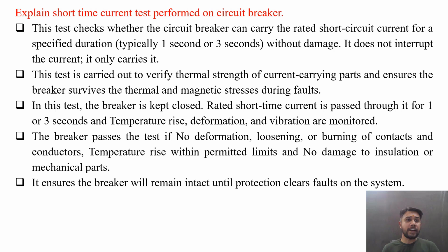It does not interrupt the current, it only carries it. This test is carried out to verify the thermal strength of the current carrying parts and ensures the breaker survives the thermal and magnetic stresses during the faults.